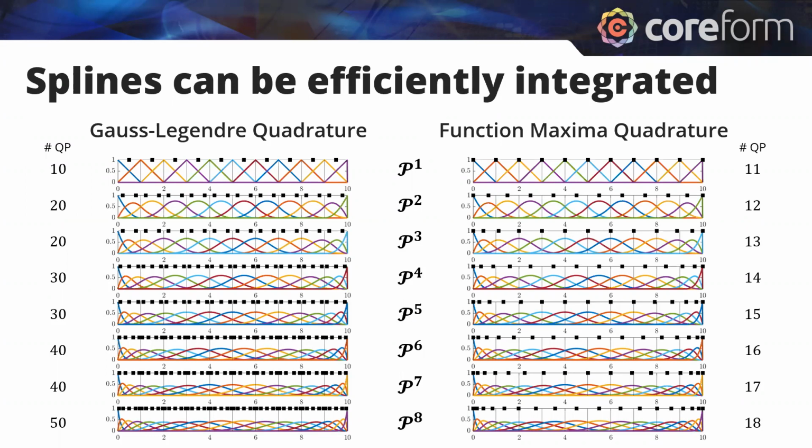Then last question, what's the advantage of the maximum point quadrature versus Greville? The benefit is that for the U-spline technology that we've developed, there's not a native concept of a Greville point. And so we don't really have the Greville abscissa for the U-splines we've created.